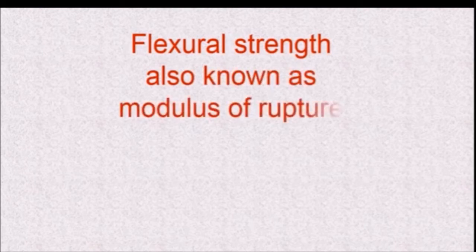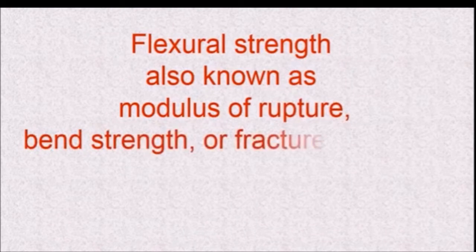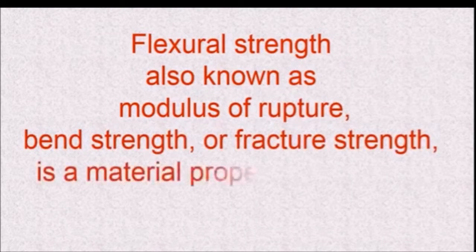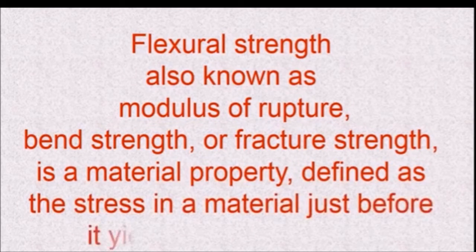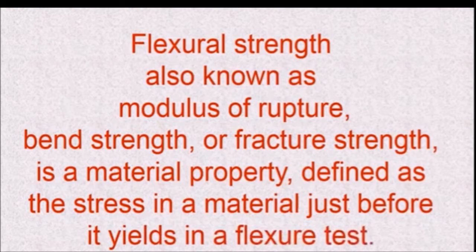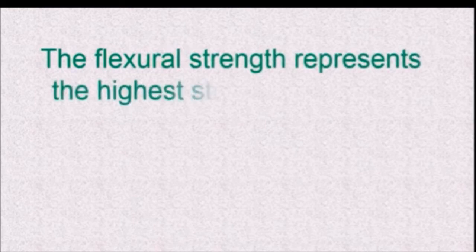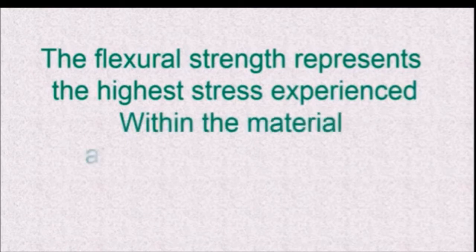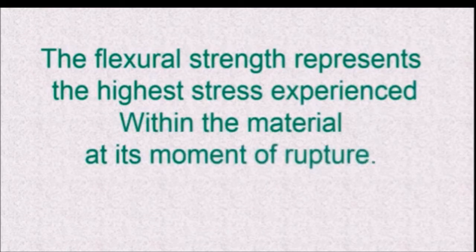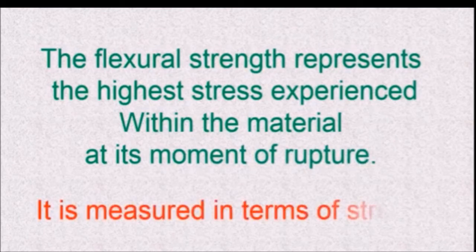Now, the flexural strength, also known as the modulus of rupture, bend strength or fracture strength, is a material property defined as the stress in a material just before it yields in a flexural test. The flexural strength represents the highest stress experienced within the material at its moment of rupture, and it is measured in terms of stress. The units are MPa, megapascal.